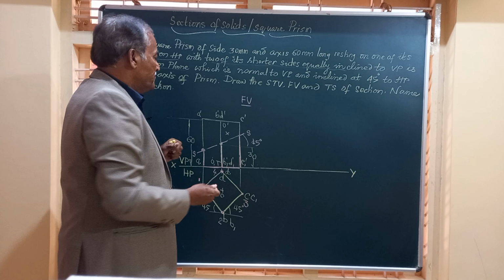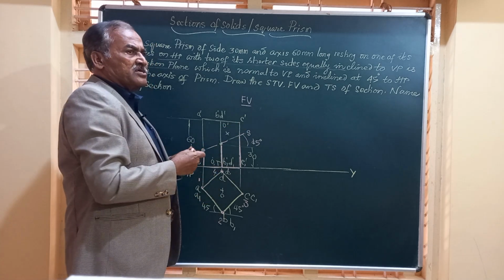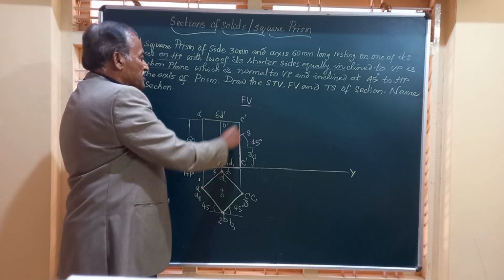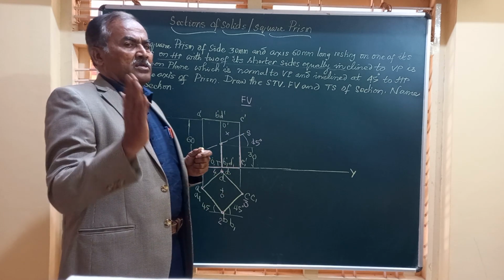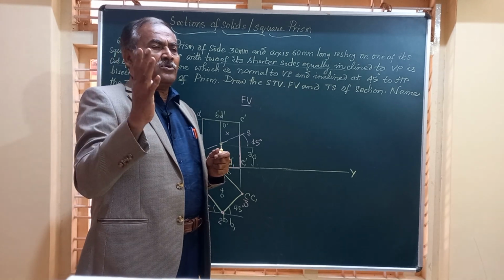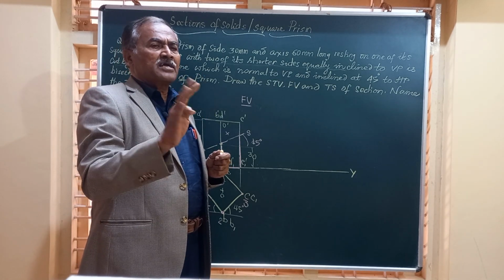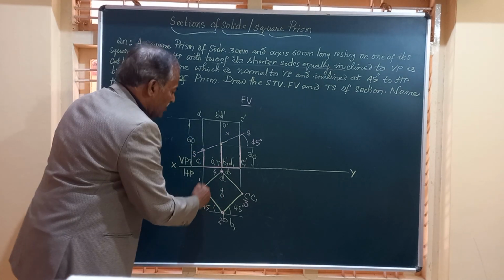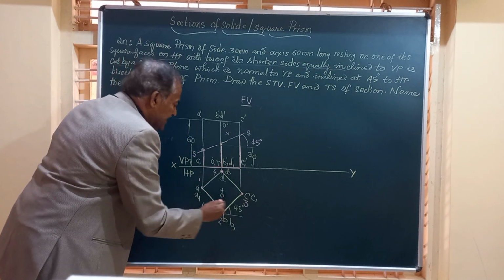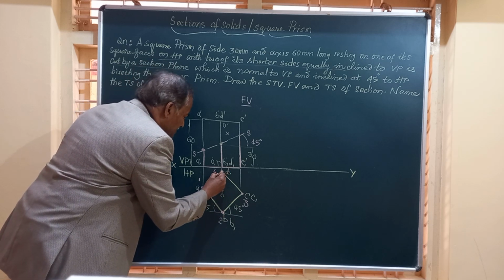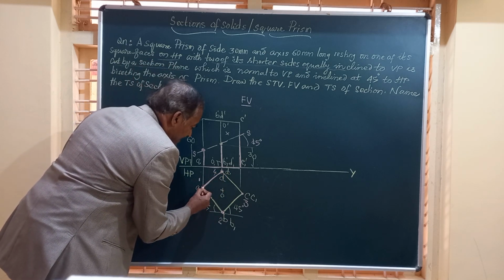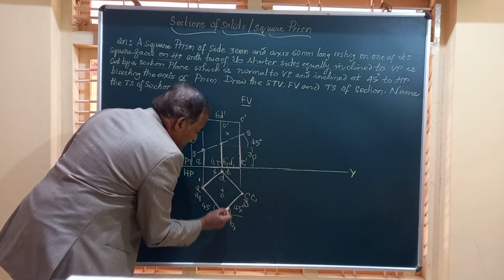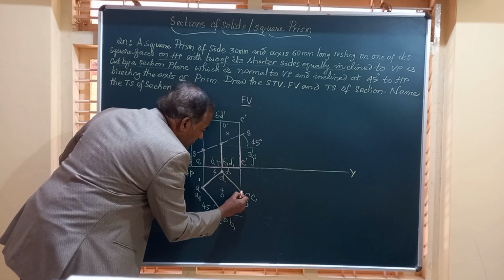So we have got all the 4 vertical edges, A dash A1 dash, B dash B1 dash, D dash D1 dash, C dash C1 dash, are all cut by the section plane. So there are four edges that are being cut, hence you get 4 points in the top view. So friends, we have got all the 4 points, and after getting that, darken this 1, 2, 3, 4 by dark lines. So this is the top face, bottom face.